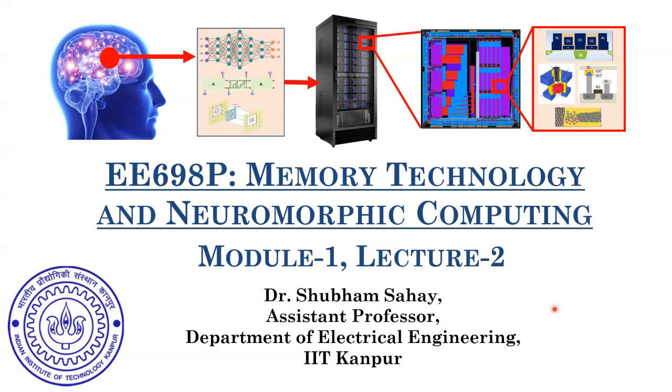Now, this cache memory as well as the registers together, since they are embedded inside your core, or present on your chip, are called on-chip memory. We have another class of memories known as off-chip memory, which starts from DRAM. DRAM is the next hierarchical level, which is also the main memory of your computing system. We also discussed that cache memories are used to create local copies of the data available in the main memory, because fetching data from the main memory is time consuming, and it's also energy dissipating.